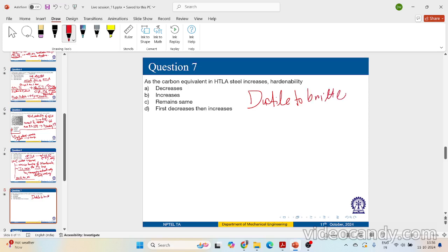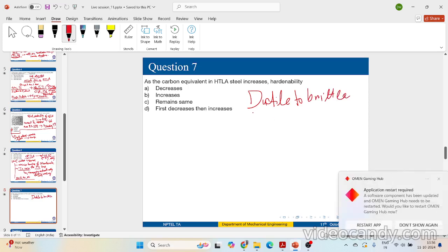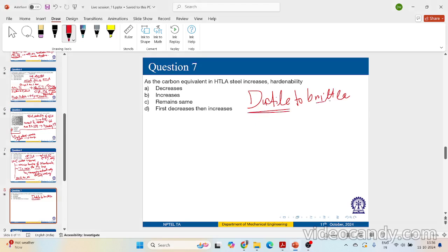As the name suggests, there will be some transition temperature after which your ductile metal can be treated as brittle material. Ductile to brittle transition. I can remember the story of Titanic. You can read that. This was a failure due to the ductile to brittle transition of the steel that was used when the Titanic was fabricated, right? That design consideration was not considered at that time. So ductile to brittle transition temperature is also very important for your steel metals. If you're interested, you can check. As I was saying, manganese, chromium, nickel, and monel will ensure the hardenability of those alloys.